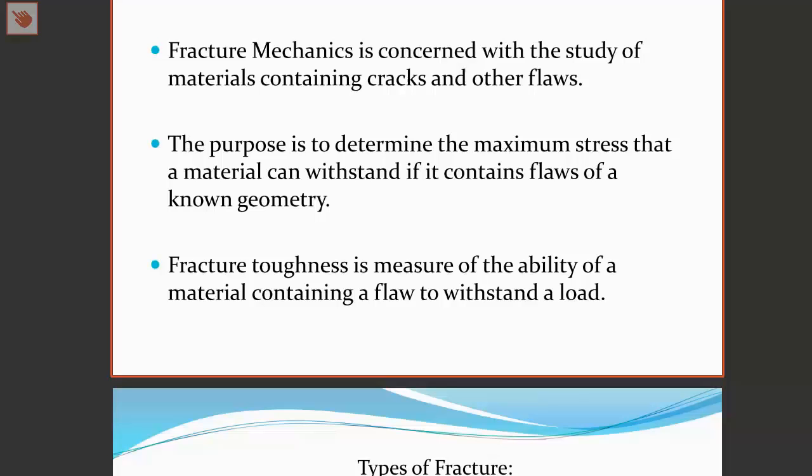Fracture mechanics is concerned with the study of material containing cracks or flaws, and all manufactured materials will contain some voids, cracks or flaws. The purpose of fracture mechanics is to study how these cracks grow, and that knowledge can be used to determine if a material containing a crack or flaw will be suitable for a certain application.